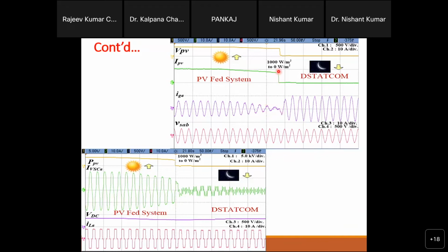So here, when power is going to zero, this is the mode change. Similarly, you can also see the PV power here, going to zero. It is the same situation. And this is the VSC. In the daytime it generates the load current as well as the grid current. But in the night time, it is only generating the harmonic current, the harmonic wave currents for the load. That's why the load currents are constant throughout the day and night.